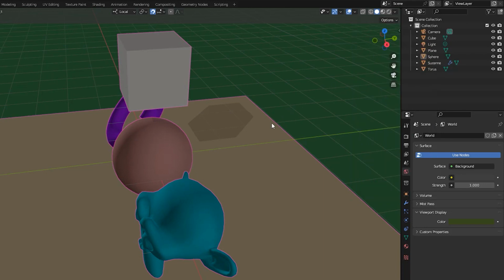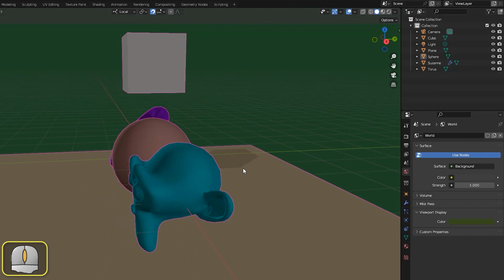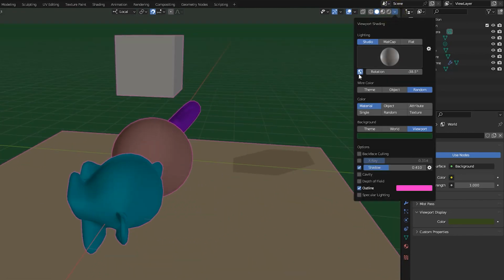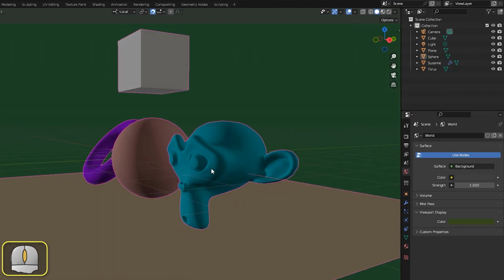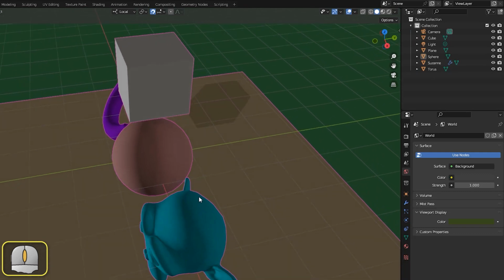The globe icon to the left of rotation is on by default. This means that the shading created by the studio lighting does not change as we move position. If we switch this option off by clicking on the globe, the shading moves as we change viewpoint. This can be clearly seen on the monkey head.